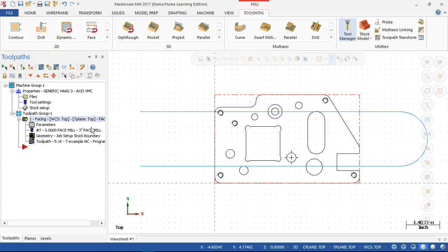All right, so I've gone from 3 passes at 8 inches a minute. That's more than 8 inches. So I've gone from potentially 3 minutes to 2 minutes. All right, so I've saved a third of my time. It's a good start. All right, if I have multiple inserts, then obviously I can feed faster.